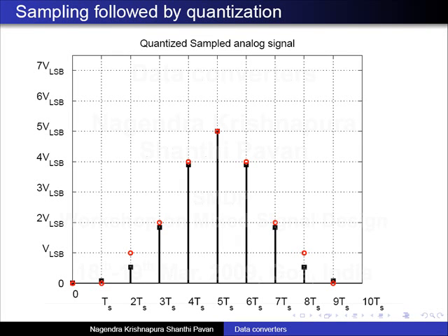Now, exactly the quantization error itself depends on the signal. Now, this is where statistics comes in, because you don't want to look at every signal and calculate every sample and calculate the quantization error from there. We want to be able to tell something about the quantization error without looking into the details of the signal. So, we use statistics. First of all, we already know one thing, that the error will not be more than VLSB by 2, if we do the rounding correctly.